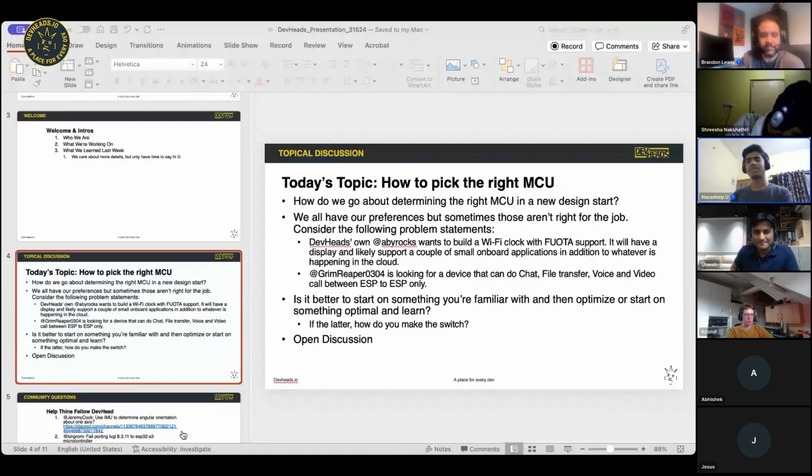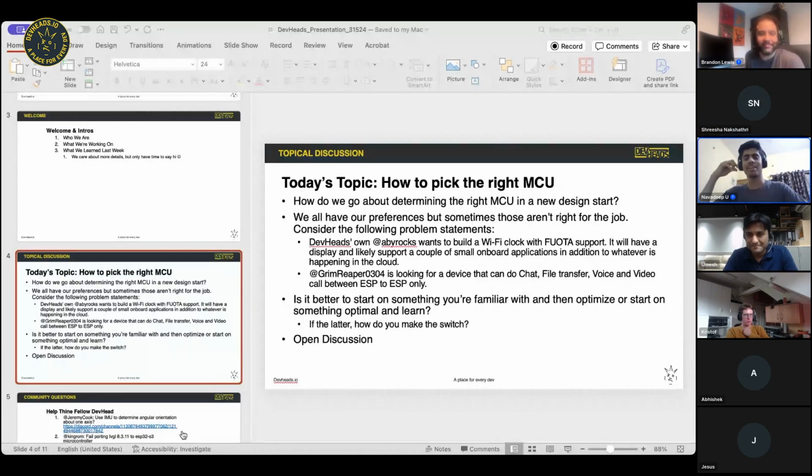Right. That's a very broad-ended question, and both the sides are uncapped. So that's a good question to start with, and it always comes when anyone starts their product development. So keeping microcontroller for product development in the core, I usually identify it using 4 pillars. Before that, it's good to know that none of the MCU is perfect, and there is always a trade-off between these 4 pillars, which you have to draw a fine line between based on what the application is. So starting with the first being the processing and what type of acceleration you want, whatever processing power you want. That would go into choosing the core, what type of core you want, what type of architecture.